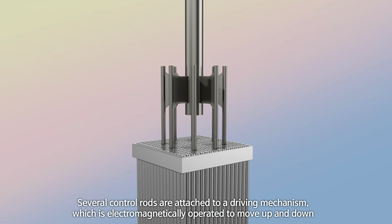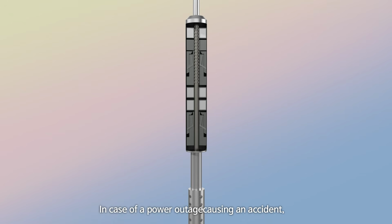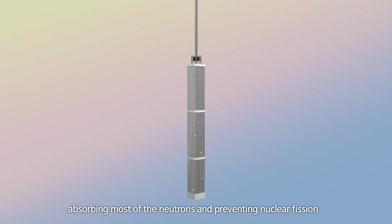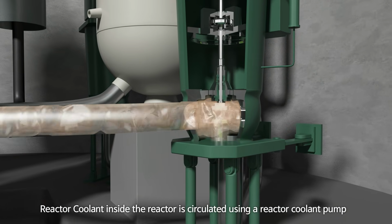Several control rods are attached to a driving mechanism, which is electromagnetically operated to move up and down. In case of a power outage causing an accident, the driving mechanism would fall freely. This would result in all the control rods being inserted between the nuclear fuel, absorbing most of the neutrons and preventing nuclear fission. Reactor coolant inside the reactor is circulated using a reactor coolant pump.